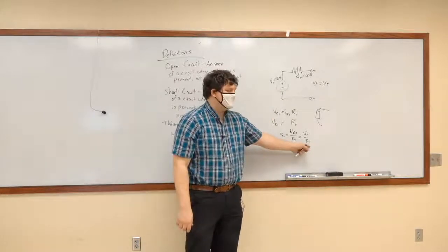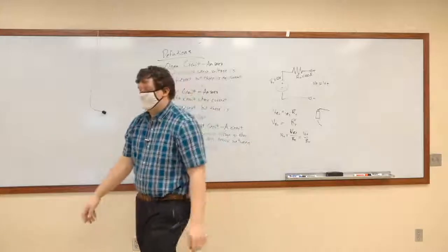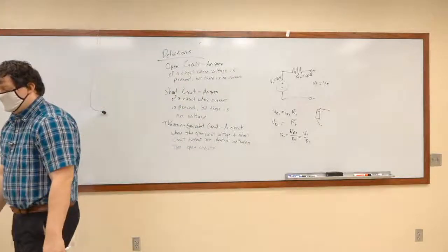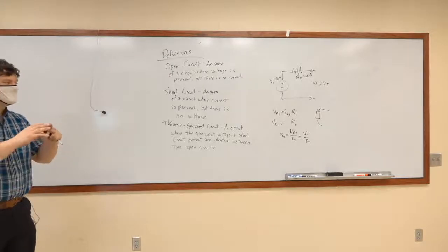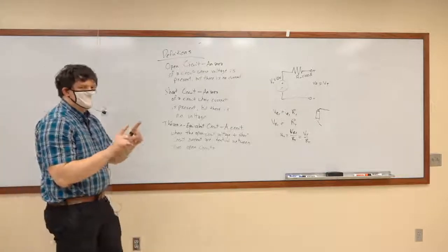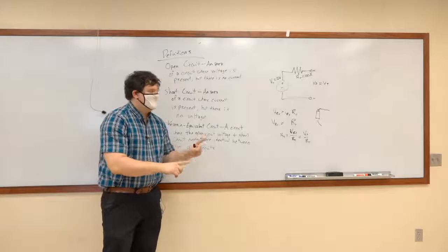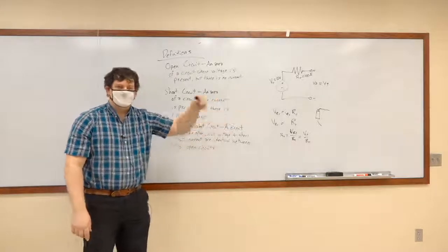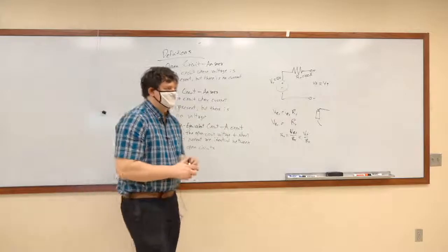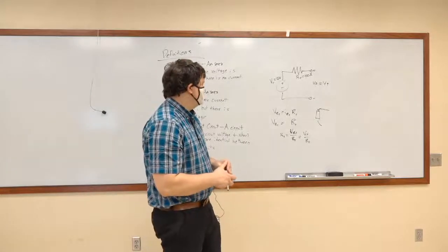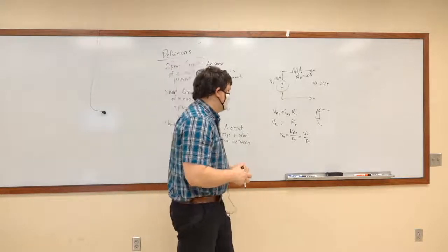And really, we can figure out RT because you know 2 of 3. So that's the principle behind an equivalent circuit. We can represent any two terminals coming out of a circuit as a Thevenin equivalent circuit just by figuring those out. Now it's kind of gross, but we can make it work.